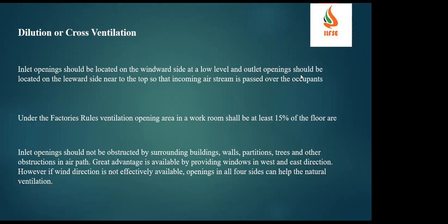Okay, the inlet at a lower level and the outlet opening located on the leeward side near the top, so that the incoming air stream passes over the occupants. Then it will just pass over the occupants so that they have good comfort. Under the factory rules, ventilation opening area in a workroom shall be 15% of the floor area.